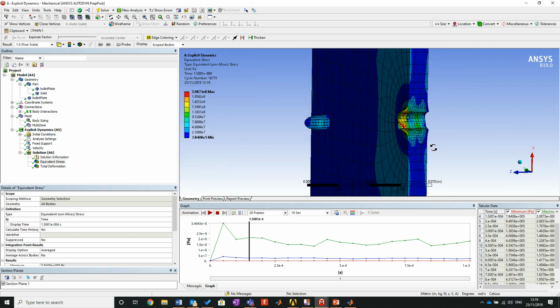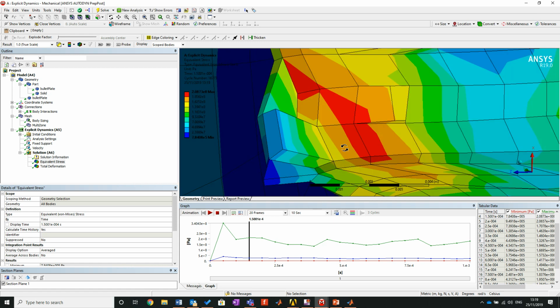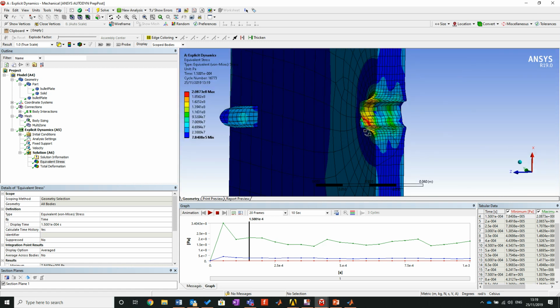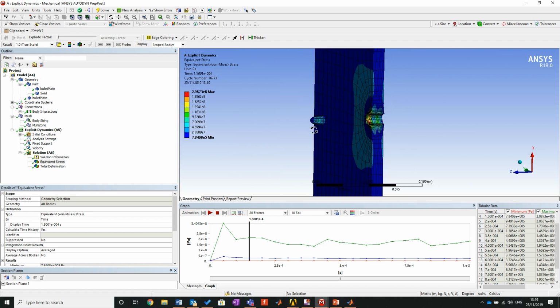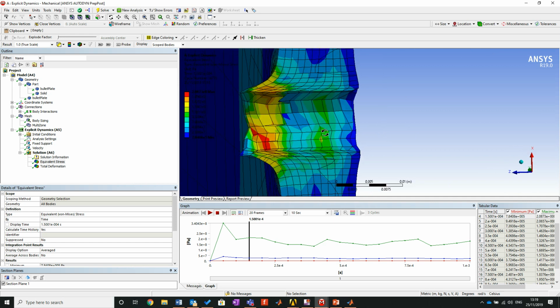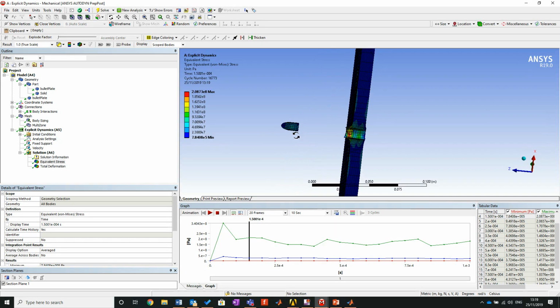You see the distribution over the actual points here. We've got energy dissipation. We've got large levels of concentration around concentrated points of, obviously, the bullet hit, but then the relation across the entire thing. We're looking at what, 9.7 to the power of 7 on the material. So, interestingly, on aluminium, it wouldn't lead to it failing. It probably allows it to be elasticated to return back. Hence the reason why it didn't do what we thought it would.